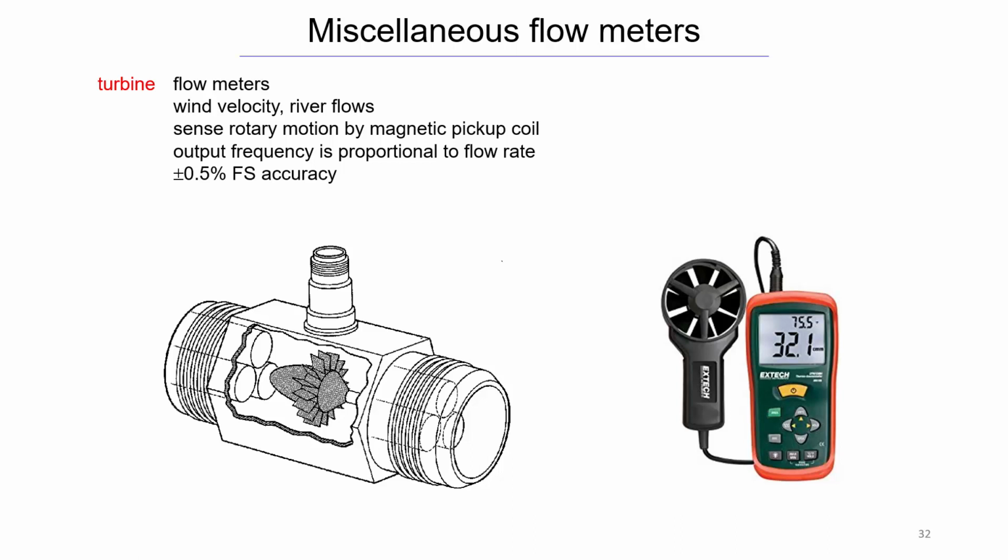Since the wire wraps around it a bunch of times, that change in the magnetic field induces a small current in basically every coil, and they all sum up together to be a signal. It's much the way that some of the less expensive microphones work, or if you play electric guitar, it's how the string vibrating over the pickup works. It's that same concept. You're transducing that mechanical motion into an electrical signal. And that's essentially what's happening here.